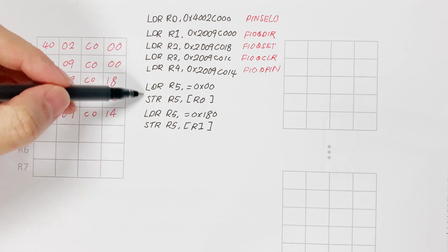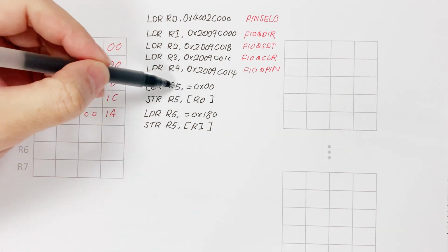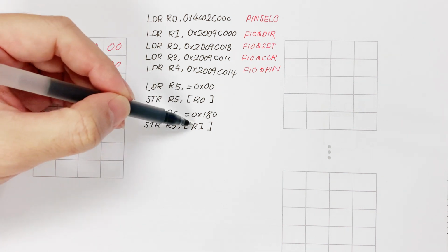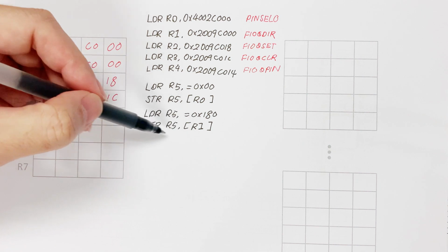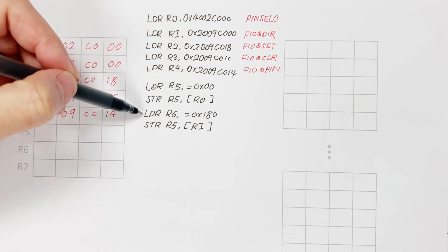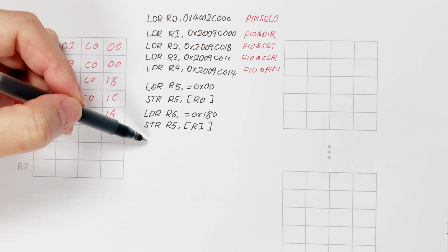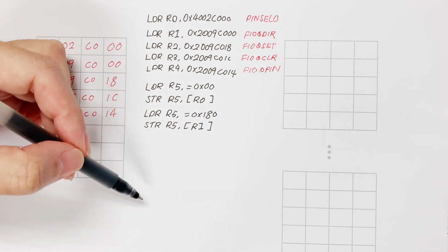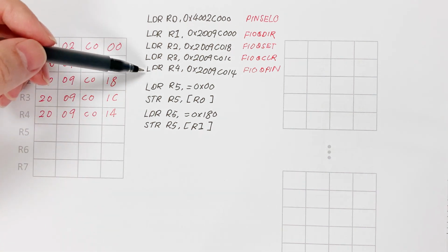Once we have done the configuration to determine which function we need to use for all our GPIO, and also which direction, or in other words, which is input or which is output, for all the GPIO that we selected, we can start to develop the logic of our alarm solution. The first thing we need to do is to read the status of our pin.